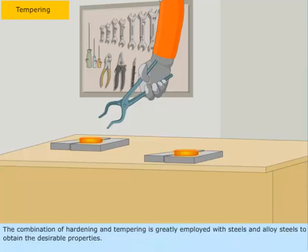The combination of hardening and tempering is greatly employed with steels and alloy steels to obtain the desirable properties. Straight carbon steels with carbon content below 0.2% are usually not subjected to hardening and tempering processes.